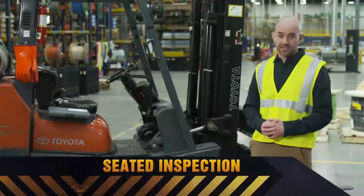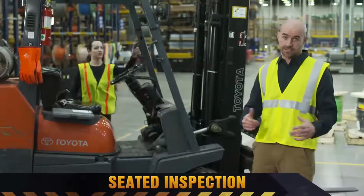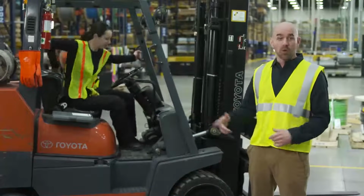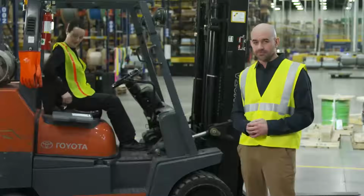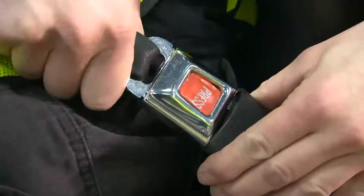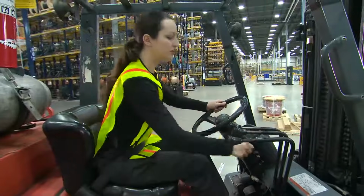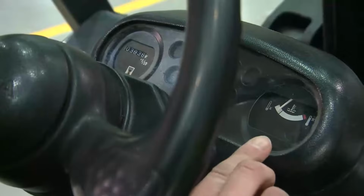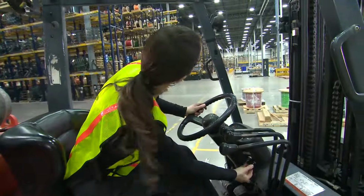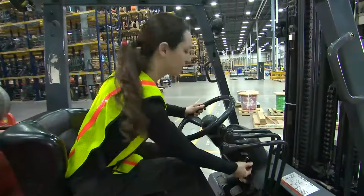To begin the seated inspection, use the three-point technique to climb aboard. Grab a secure part of the forklift with each hand and put one foot securely on the forklift. Settle in and secure that seatbelt. It needs to buckle and tighten for a good fit. Stay seated and turn on the forklift. Look over the gauges, warning lights, and battery or fuel levels. Check your safety equipment, including lights, to make sure it's all working properly.